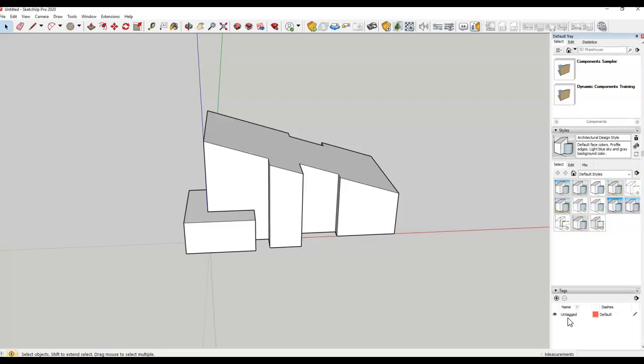Like if you want to turn things on and off because of an animation reason or a work reason or other things, then use them in that case, but only apply the layer to the group level, not the object level. There's always exceptions to every rule, but just as a basic learning, that's going to be easiest. And in fact, in this video, we probably won't use layers at all, that just keeping everything untagged is fine when you're working in SketchUp.